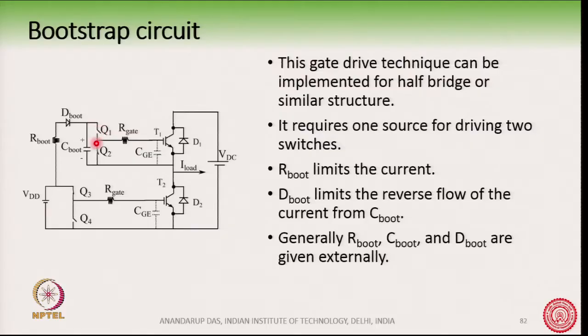Q1, Q2, Q3, Q4 are also part of the gate driver circuit, inside the IC. What you have to give externally is the R boot, D boot and C boot, the resistance, diode and capacitance, and along with that, if you want, you can give the R gate externally.